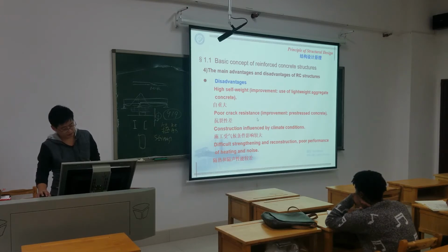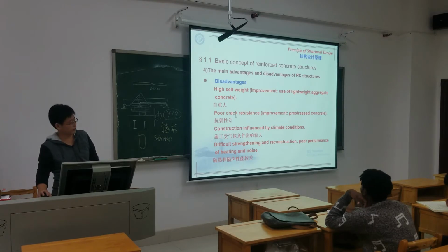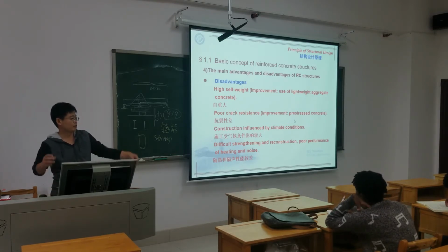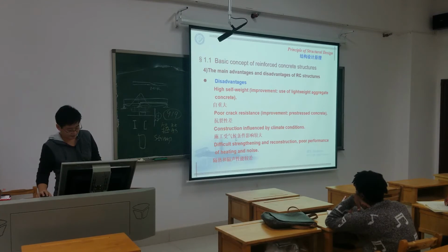The poor crack resistance. It's easy to crack because it has very poor tensile strength. So how to fix this problem? Use the pre-stressed concrete. Push first, make it not easy to crack. And the construction is influenced by the climate.